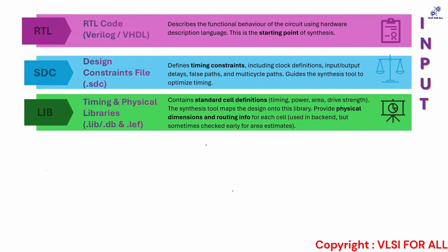for example, I can upsize the drive strength. It says: I currently have a 2 drive strength cell, let me look in the library if a 3 drive strength cell is available. It finds that no, a 3 drive strength cell is not available. Then it can again search in the libraries: do I have a low VT flavor of my design? Low VT is a faster cell, and because my setup timing is being degraded, let me try swapping with the low VT flavor. So I see that I have a low VT flavor in the design, and now I can swap it.